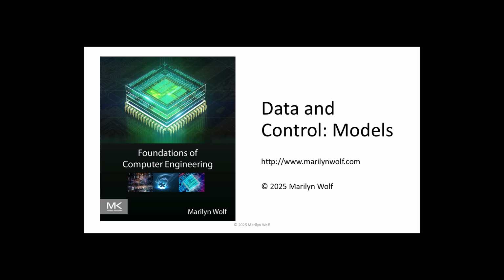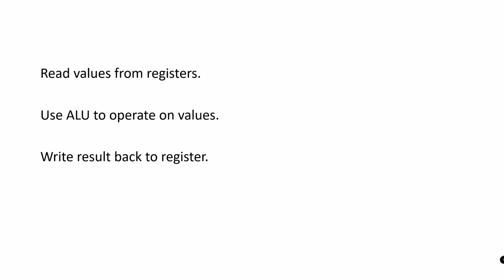The datapath controller machine is a foundation for the design of CPUs and many other types of digital systems. One or several data values are read from registers in the datapath. Operations are performed by the datapath's ALU. The result is written back to a register.